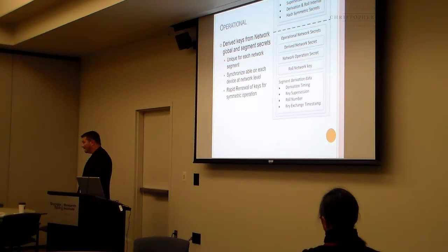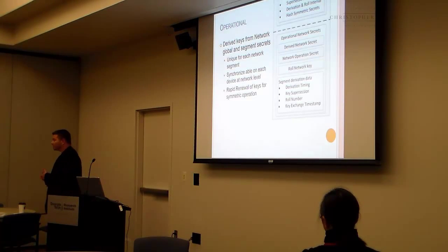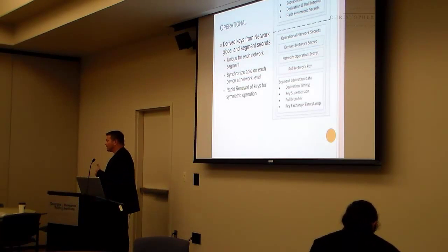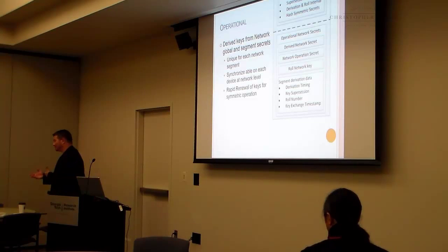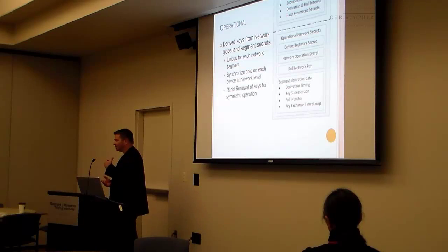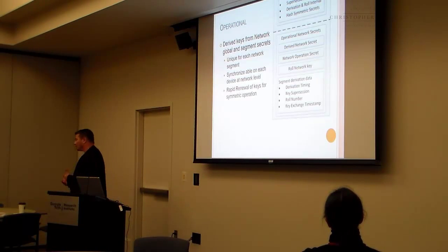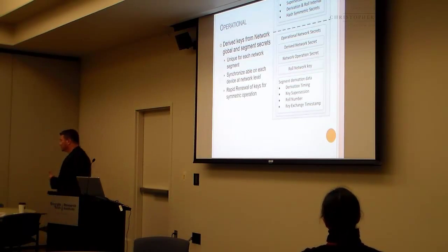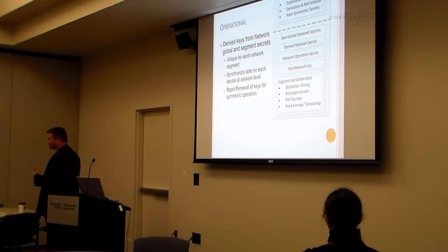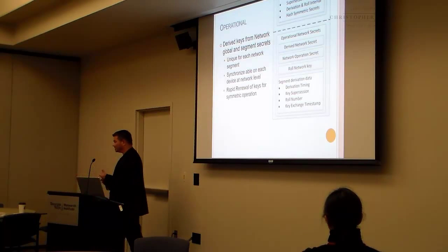Absolutely, that's why you see that I'm showing keying for symmetric and asymmetric. Anywhere that there's a human-based operation, something that's queued, you use asymmetric cryptography because that's what is used in the IT world. But if you have rapid communications, it's done all the time. These systems can use symmetric cryptography to communicate and be within those defined time requirements. They can actually use these two different processes in both instances.